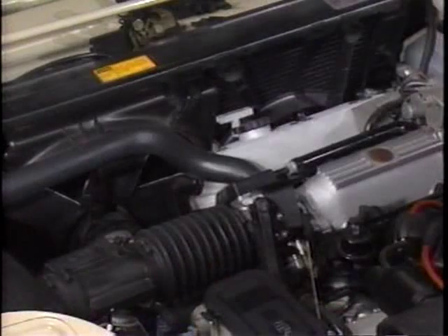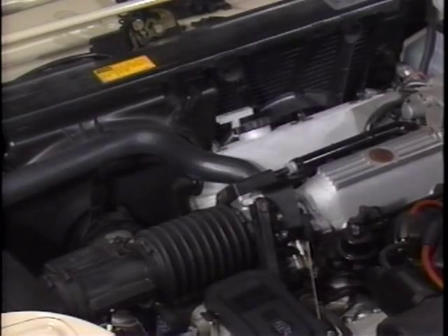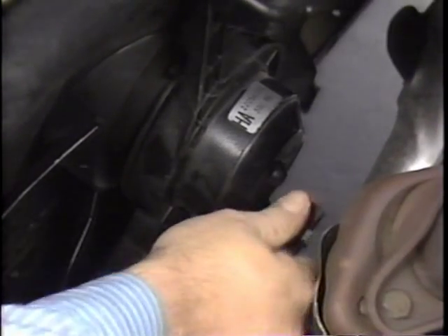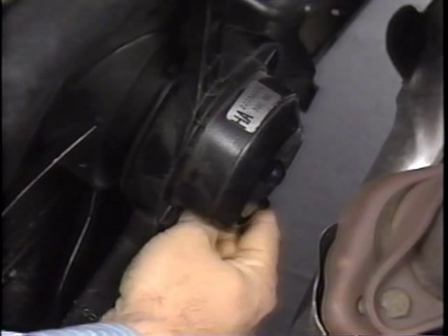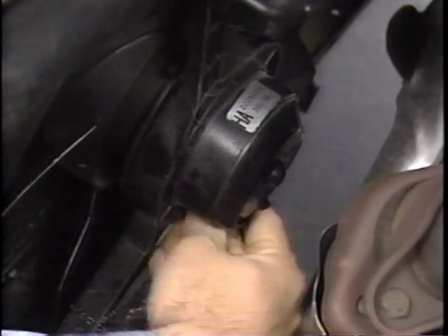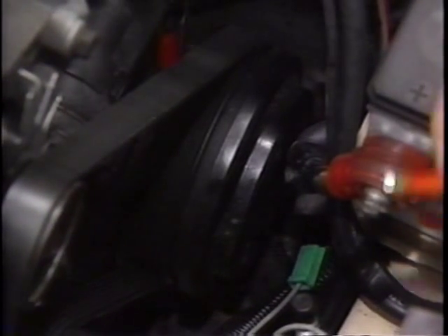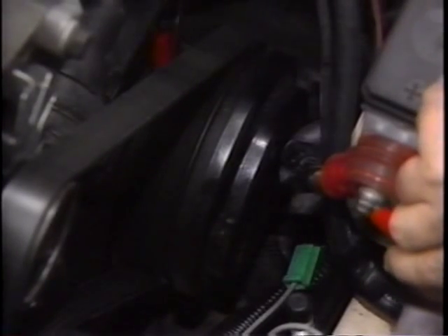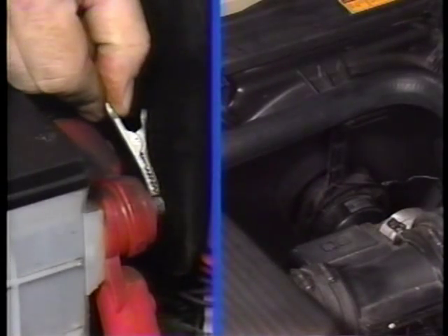On CCOT systems, check to see that the compressor clutch engages properly and that it is not slipping by observing it for 2 or 3 cycles. And check that the electric cooling fan comes on. If the fan or the compressor clutch fails to operate, check for obvious causes like burned out fuses and burnt or disconnected wiring. One simple test you can make on the clutch is to jump it to ground and to the hot battery terminal. If it engages when powered in this way, the problem is not in the clutch itself. And you can check the operation of the electric cooling fan motor in the same way.